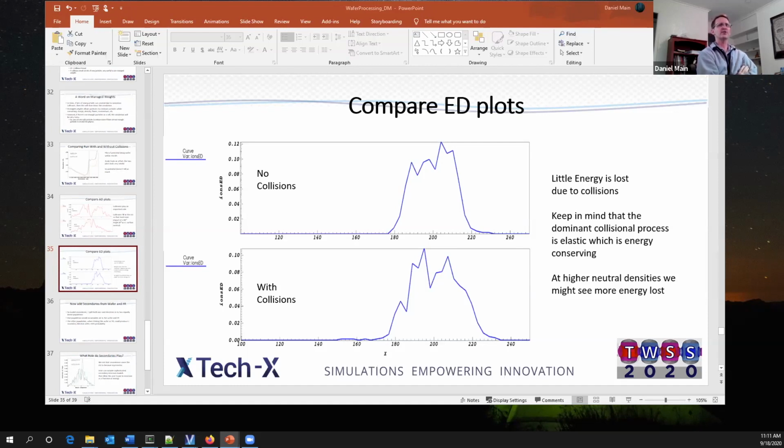I think I ran these on 6 cores. They took a couple of hours on 6 cores on a Windows machine. Overnight, just do 5 or 6 runs, or even more. You could set this up as a batch, so that one ends, another one starts, and then you come by the next morning and you've got 15 or 20 simulations to analyze. That's the nature of this sort of nonlinear modeling. But that's the power of it too.